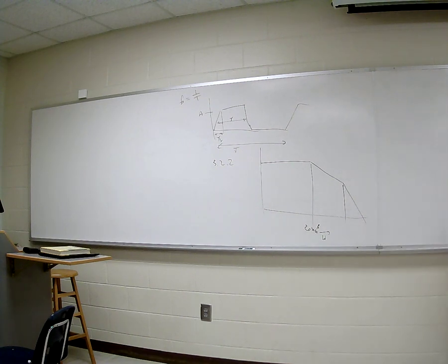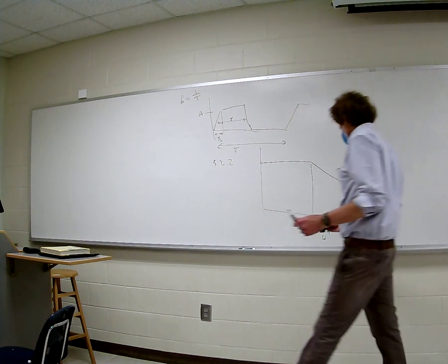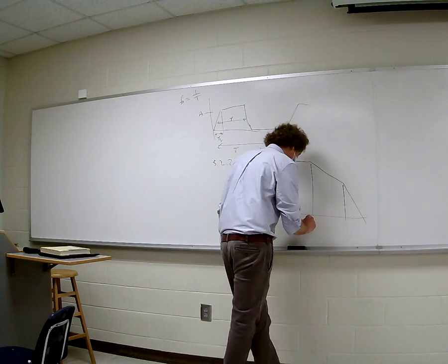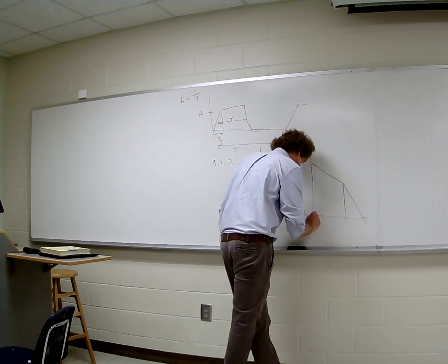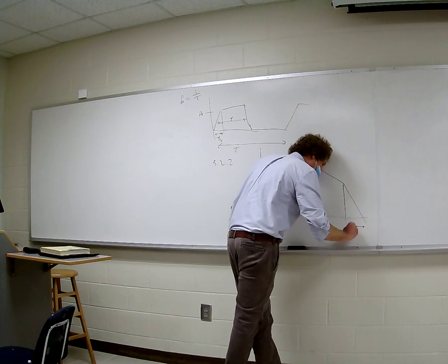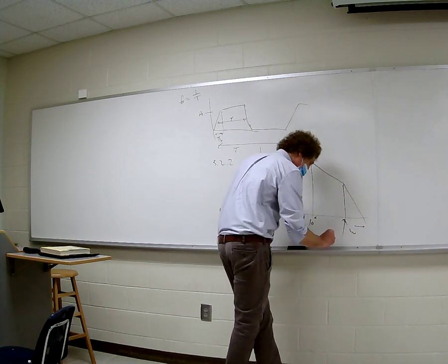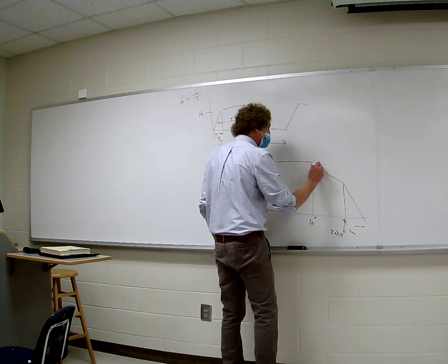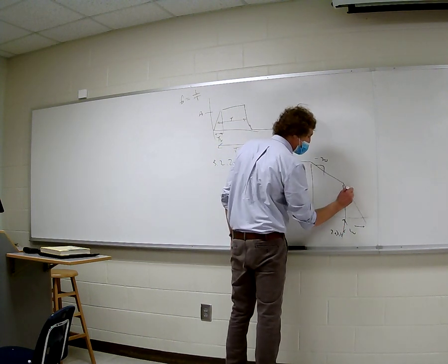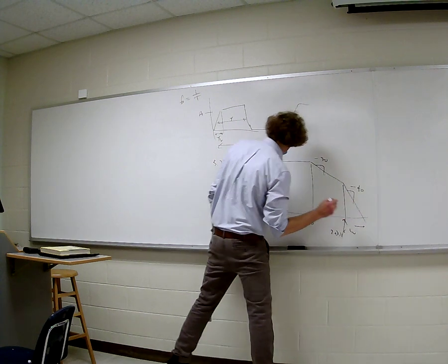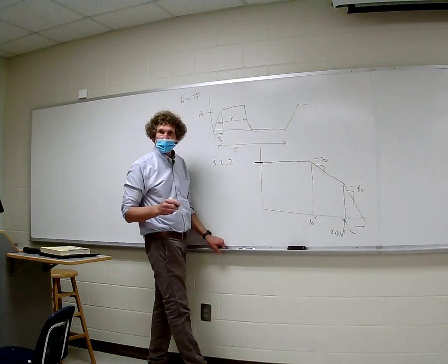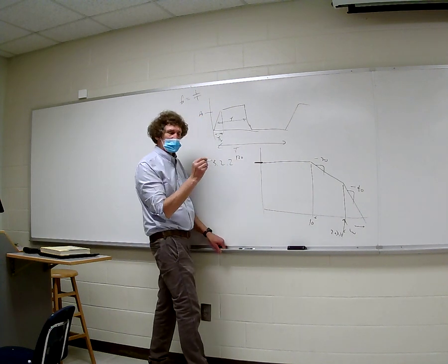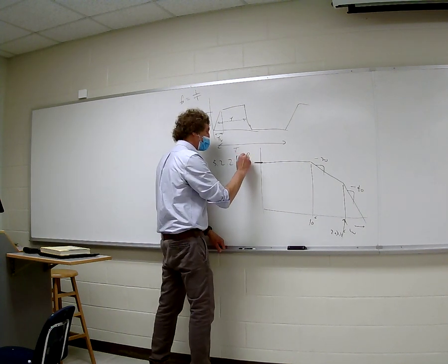So it's a megahertz. This is omega, not F, but it would work the same way. So this is going to be 10 to the 6th, and this is versus omega. Now what's the other one here? 20 times 10 to the 6th, and that's omega 2. And this slope is going to be minus 20 dB per decade. This is minus 40 dB. What's the starting point here? 120 dB microvolts.